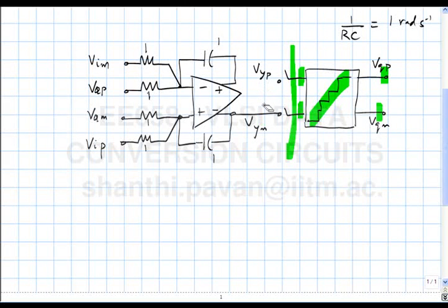And see, these are all sampled data systems. So it's not like you can do an operating point and figure out that you have made a mistake. All right. So you run a transient and you'll find that the stuff just gets stuck at the maximum level of the quantizer. That's how you learn that you made a mistake in the sign. Does it make sense? Okay.